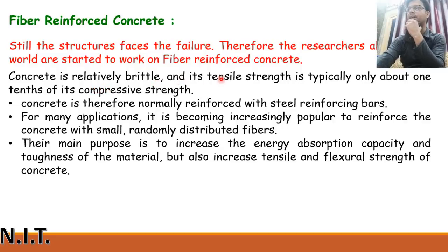Concrete is relatively brittle and its tensile strength is typically only about 1/10 of its compressive strength. These two lines are for plain concrete. Concrete is therefore normally reinforced with steel reinforcing bars. For many applications, it is becoming increasingly popular to reinforce concrete with small randomly distributed fibers.